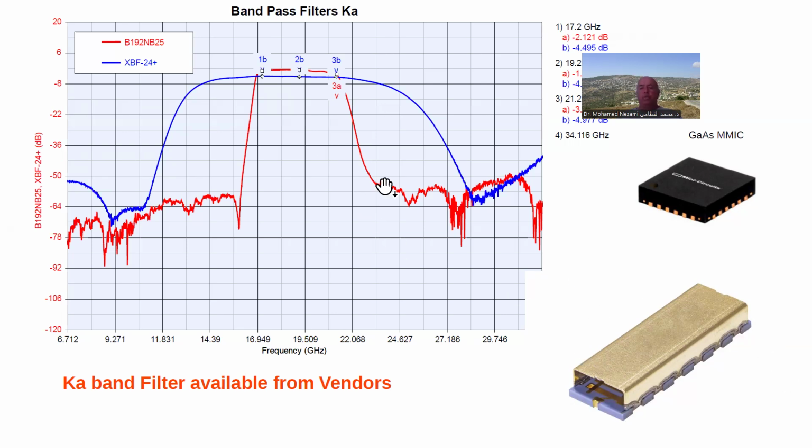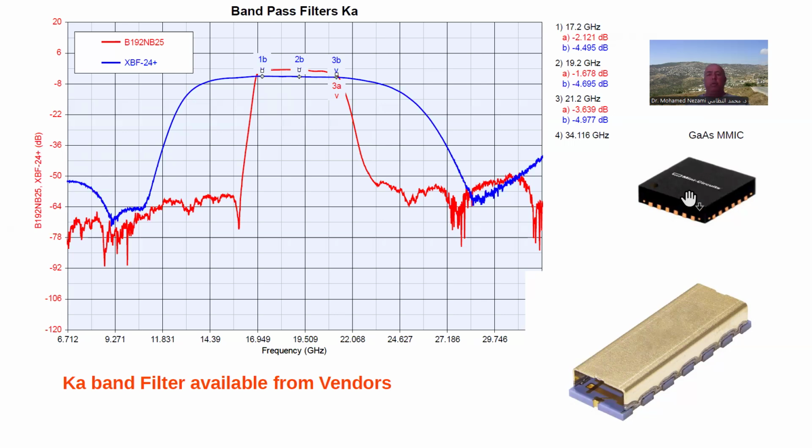So I chose to just go ahead and design my own. There is a filter for Ka-band SATCOM systems available from Mini-Circuits, a GaAs pHEMT MMIC-based filter. You can see it in here. It's a bit wide, and I can't really use it. Maybe they did it for 5G, but it's not going to work for me, especially since the loss is excessive. It's nearly 5 dB of loss. Okay. Now, if you're interested, these are the part numbers for these two parts in here.